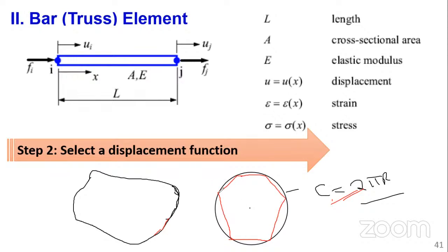So basically what we are saying, you see at the nodes, this is where our finite element touches the actual curve. Of course, we know this. So at the node is only where we have the actual solution, what we can call actual or exact. Number two, at the node, this is where we have the known values. So we have the known value here, we have the known value here. Whatever else in between, we can approximate by interpolation.